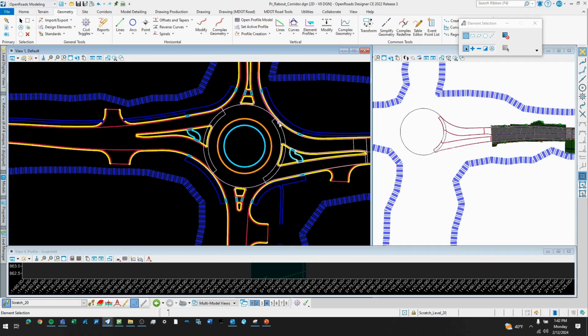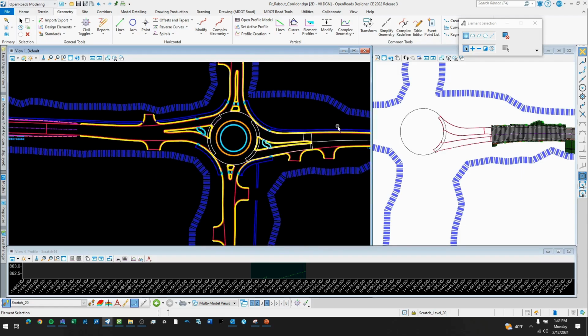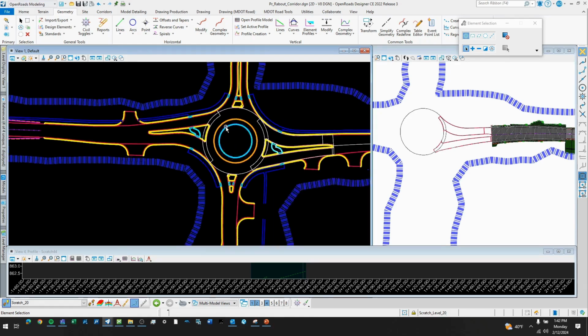Another consideration had to do with drainage: where do we want water to be flowing, where do we want our high and low points along this ICD. And then the last one is the cut and fill volume. Does it make sense in terms of an earthwork calculation? How high do we want this ICD to be relative to existing ground? And then those tie-in points too, like what's going on outside of the ICD as it approaches, so that we can optimize that drainage.